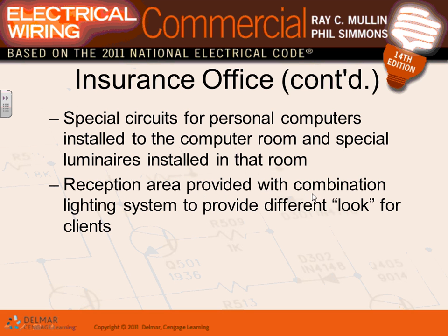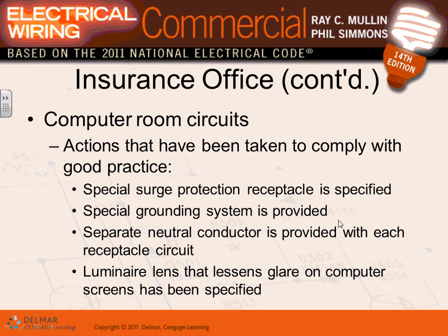Okay, reception area: a combination of lighting systems to provide the look for the clients. So they have a different type of reception. Computer rooms: in the computer room, guys, they also have special surge protection for receptacles. Computer rooms have a lot of very expensive equipment, so they have surge protective devices. If lightning hits the transmission line, instead of burning your electronic equipment, a surge device will pop and will most likely protect your equipment.